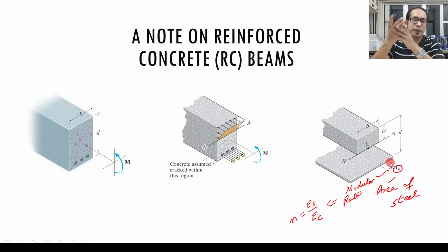Now this method of solving reinforced concrete beams and essentially designing, see, the whole point of designing is that you're trying to find, to resist a particular tension, how much steel do I need? Do I need 3 bars, 4 bars, or what grade of steel do I need, right? This method of designing beams used to be a very integral part of what was previously known as the working stress method. Now in the latest code, this has been revised.